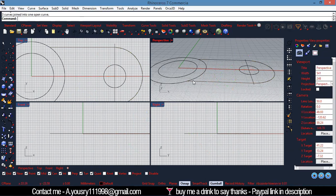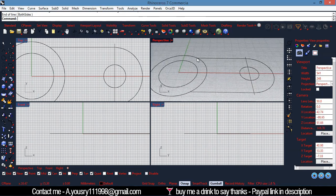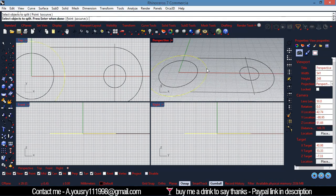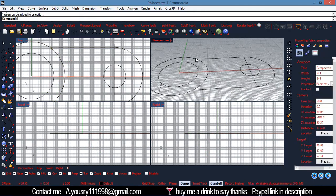And I also need that, or I can just close the shape that way. But I don't like to do that. The way I'm going to do it, I'm going to split this curve. And the way I go to the split command, this split command asks me to select the objects to split. I want that one to be split, and press enter. And then the cutting objects, these lines, hit OK. So that is split from my circle.